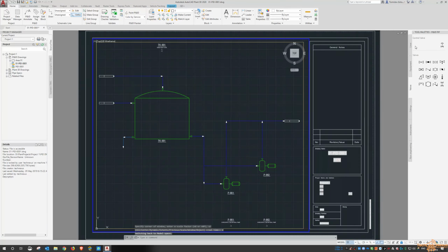But ultimately, whoever is administering it will, or should, hopefully have their project set up and have all of the line types already set, so you don't need to bother trying to set things up as an end user. You can see here with the instrument lines, if I need to place an electrical signal, pneumatic, hydraulic, software, capillary, supply lines, leaders, electromagnetic and mechanical lines. We might have a look at them in a second once we place some valves in here.